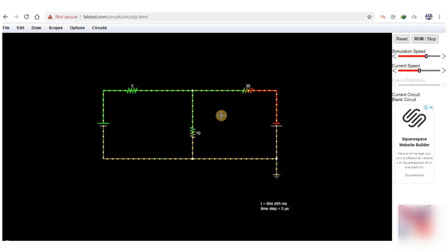As mesh analysis is for finding the currents of the circuit, but here we will verify the voltages and current both. So first we will place voltmeters on the respective resistors and check whether KVL is verified. If KVL gets verified for the meshes, then it means that the mesh current will be exactly the same that we found during our calculation.